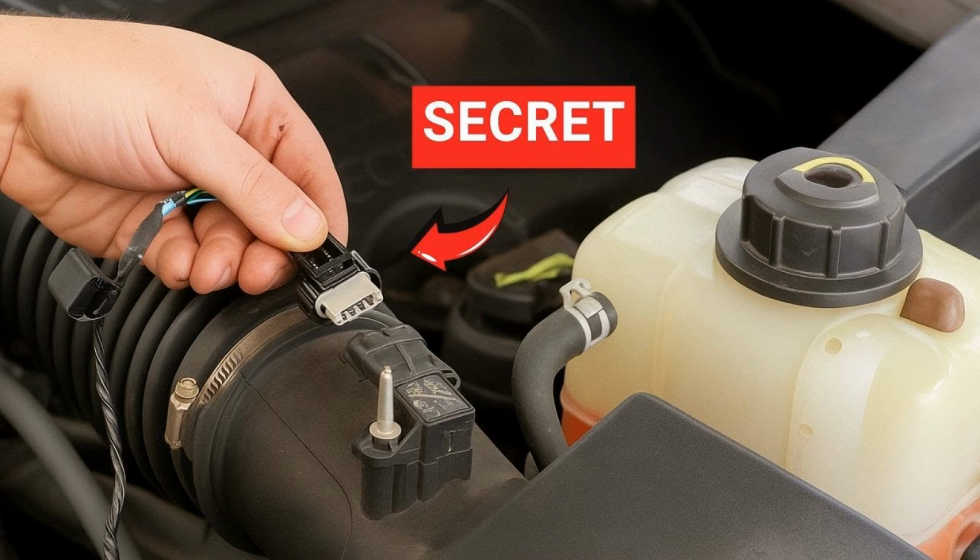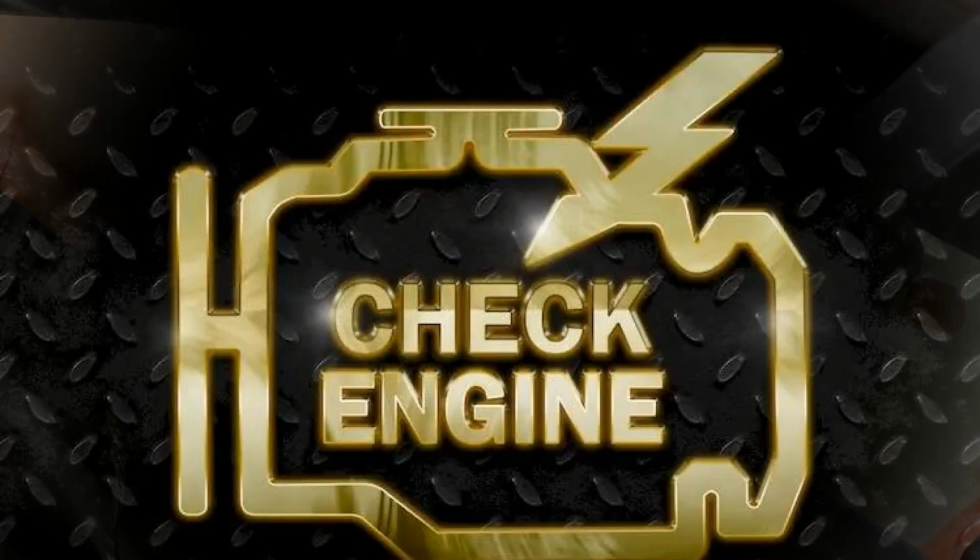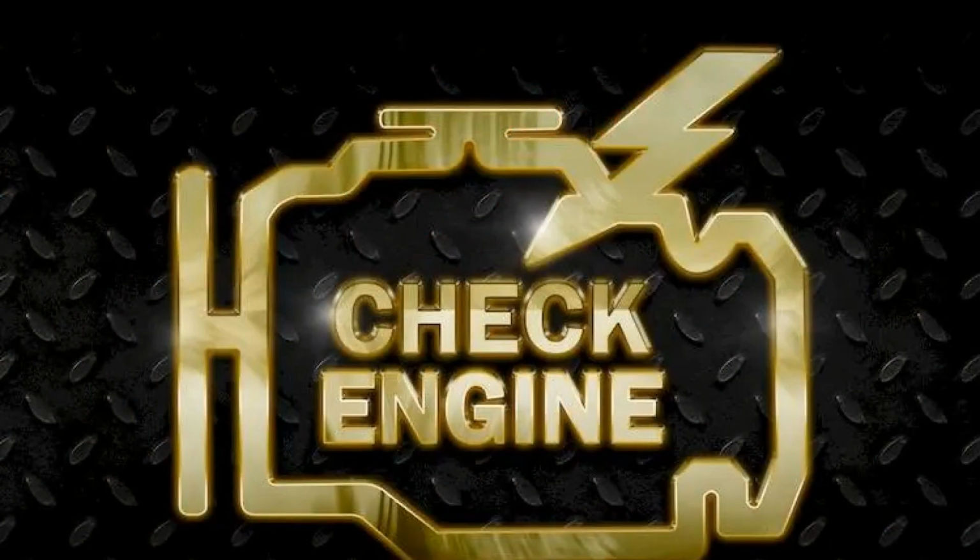Common errors when diagnosing code P0582. The most common mistake here is to replace the cruise control vacuum solenoid when the real problem is the one-way check valve. A full diagnostic will ensure that all components are inspected and the real underlying problem detected. Blown fuses are often a hidden cause here, although they usually point to another, deeper problem.